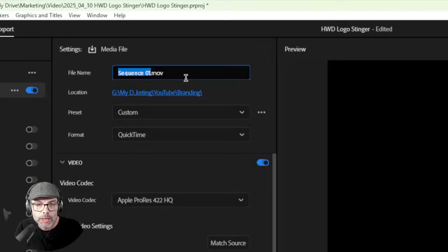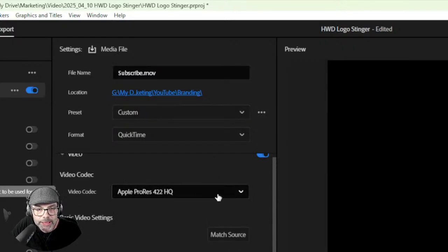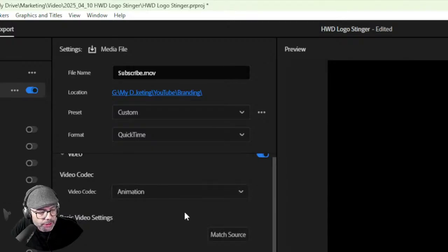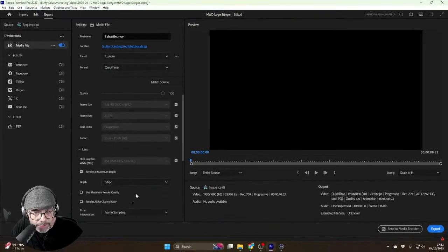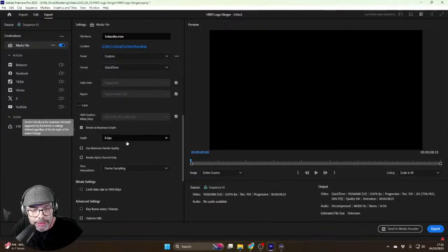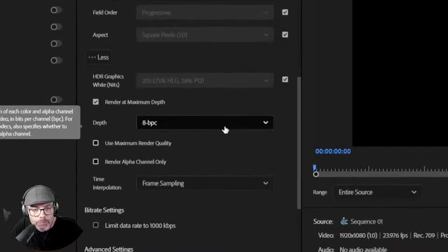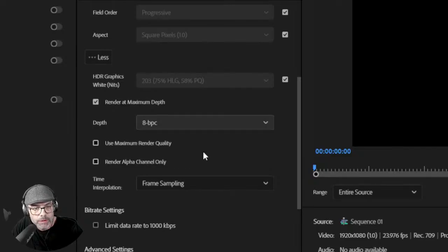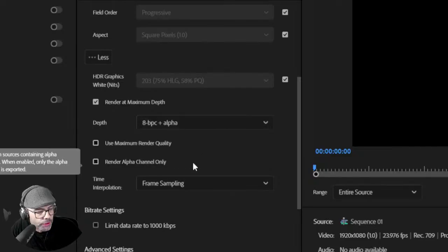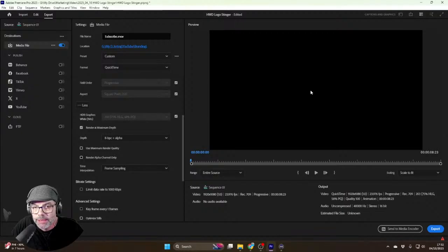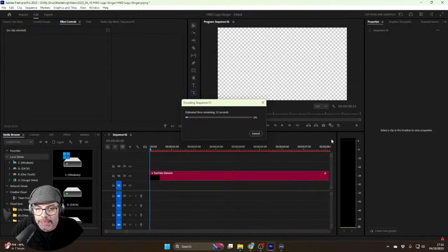I'm going to call this, let's just call it subscribe for now, and I'm going to render it into my YouTube branding folder. Nice. And we just need to change the codec now to animation. That is going to make sure we've got all the settings available to us further down here, because it's this depth that we want, and we need to change it to BPC plus alpha, and that's going to make sure the transparent alpha mask gets sent as well. So now we're going to go ahead and export that.